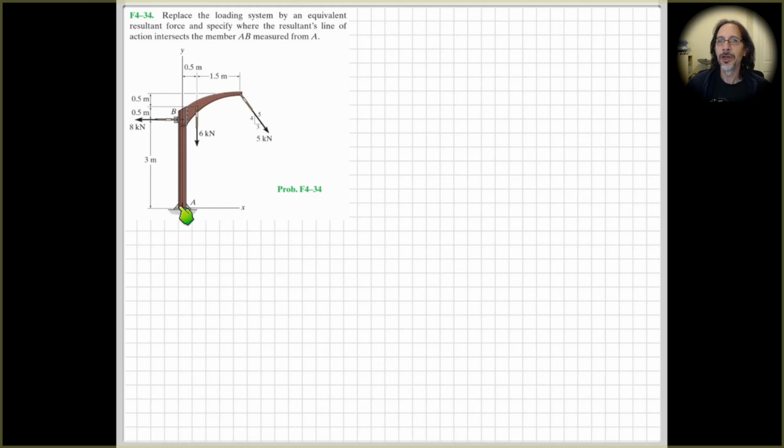So in order to size those welds and bolts, usually what we need is the normal force, the shear force, or the tangent to this section, and the moment that's applied there. All right, so let's do the problem as it's written. So our solution will be first to find, as I said, the equivalent force and moment at A.